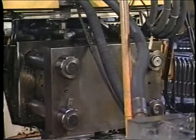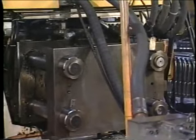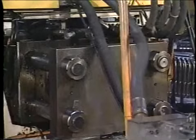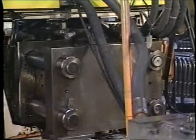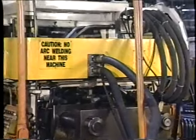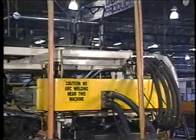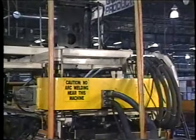Another potential problem with cylinders is hydraulic shock. Sometimes this shock can be severe enough to damage the cylinder. Many cylinders include a cushion to slow down the piston as it approaches the end of its stroke. This reduces the shock and helps prevent damage to the cylinder and the system.